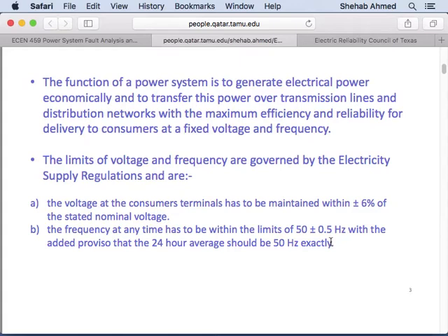So there are two rotors spinning at an average frequency of 50 hertz, and you will see the other rotor as if it's stationary with respect to you, right? But there may be some angle deviation. If it's loaded more than you, it will be slower. It will lag a little bit. If you're less loaded, then you'll be faster, right? So you will see some relative motion in that case if one is loaded versus the other, right?